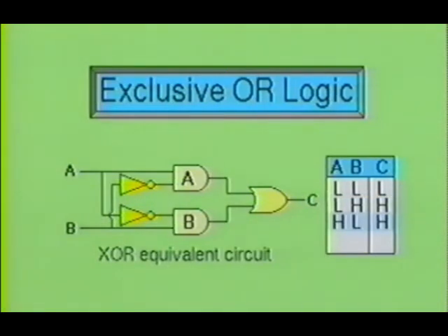Next, we will make input A high and input B low. Our truth table shows that there will be a high output at C. We will now see how this happens. When a high is applied at input A, it feeds a high into 1/2 of gate A and a low into 1/2 of gate B. When the low signal is applied at input B, it feeds a low into the second half of gate B and a high into the second half of gate A.